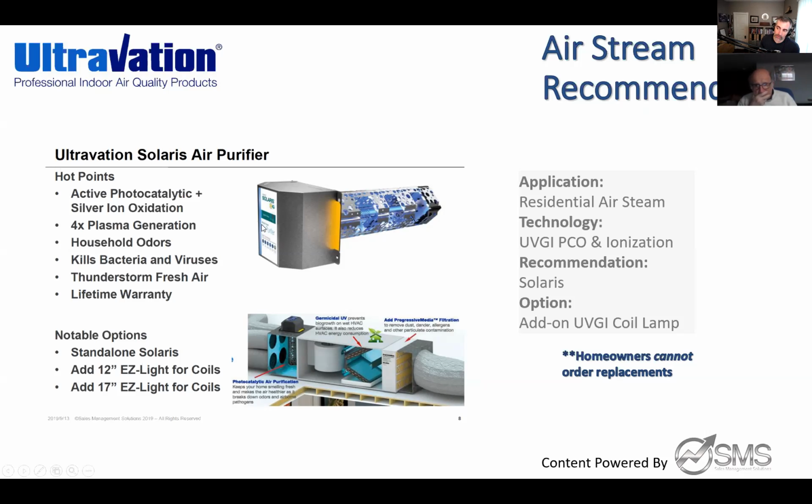When you take this power head off, after you've installed it, there's actually a slide arm inside there. This has a special dual band bulb in there where we can actually adjust the amount of UV being emitted and the amount of PCO being created. And the rating on there is based on either CFMs or square footage. So I can easily tweak this up to 5,000 square feet of treatment down to as little as 500 square feet of treatment. So you can scale this and make it adjustable, and you might be able to remove that ozony smell problem if that person's not too sensitive, and you'll be fine. You won't have to worry about it being a non-ozone product.